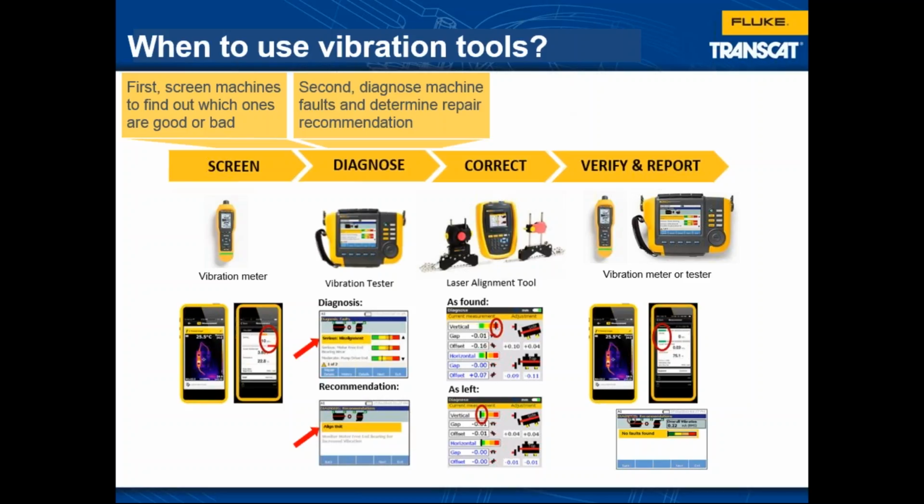Second, we would diagnose the faults. Just like the doctor would tell you what the problem is, and more importantly, what to do to fix it, and the root cause of that problem. An example down at the bottom, it might be a little small to read, says serious misalignment, and the recommendation is to align the machine.